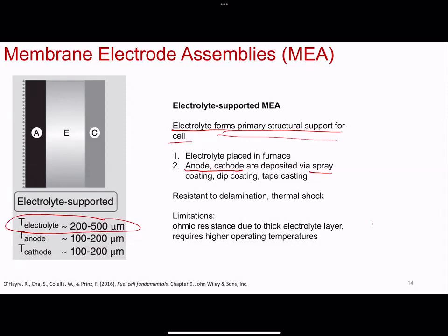Dip coating is slower, so that's not as preferred. Also, you need a huge volume of solvent that you now need to dry off, so that's not as ideal either. In terms of recycling the solvent, if you're evaporating it, maybe you can collect it somehow and reuse it, but there's no guarantee that your solvent is 100% pure again, unless you do filtration. But dip coating is typically longer than spray coating.